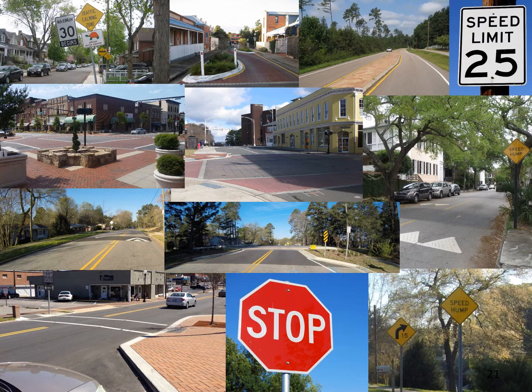Speed limit reductions in and of themselves don't tend to be very effective, but they are fairly popular, as well as stop signs as a traffic calming device don't tend to work that well, but are again very popular. So there are lots of options out there. Some work better than others. A lot of cities have programs or plans or a toolbox that they'll use to implement some of these, experiment with others, and hopefully come up with something that works for their community and is effective and efficient.